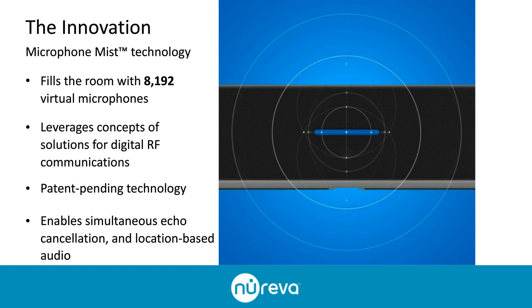So essentially, if you think about beamforming, if you've got X number of angles from the front of the room that you can pick, an angular slice, what you're actually doing is taking advantage of this extraordinary amount of processing to figure out the intersection point of those microphones to figure the distance as well. So you're adding distance in addition to angle, which allows you, instead of having 16 or 24 angular slices of the room, to have over 8,000 individual points that you can identify. So that's why it takes so much processing, I'm assuming.